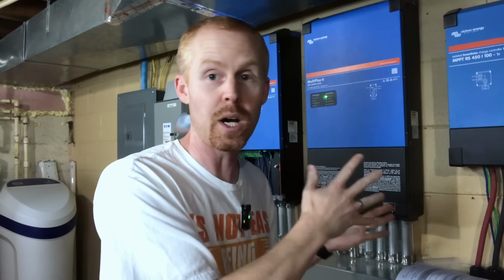And so now, when the relay on the Cerbo is open, your AC input relay will be open as well. And when the relay on the Cerbo closes, that will close aux2, that will close aux1, and then AC input will turn on.